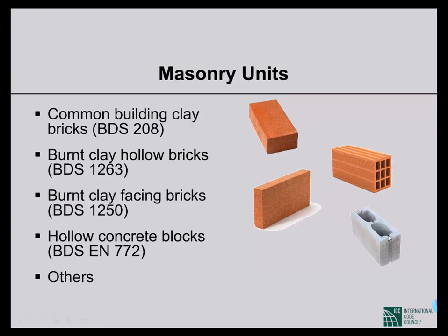You can place reinforcement along these grooves, and you can place vertical reinforcement through the cell, and you can grout the cells. So this type of block is very useful for reinforced masonry. And they are environment friendly too, because burnt clay is not very friendly for our environment. That's a different story, but I think most of you are very much aware that burnt clay is quite damaging for our environment.